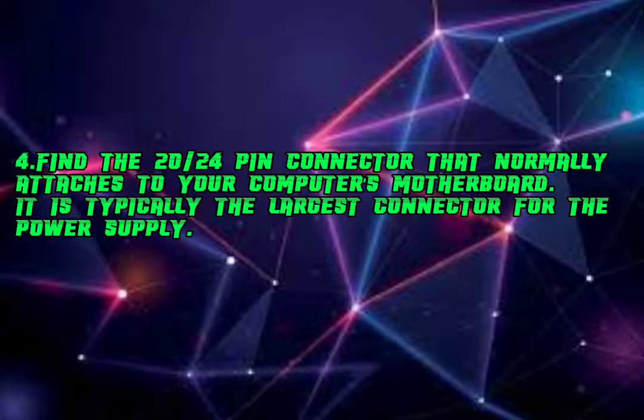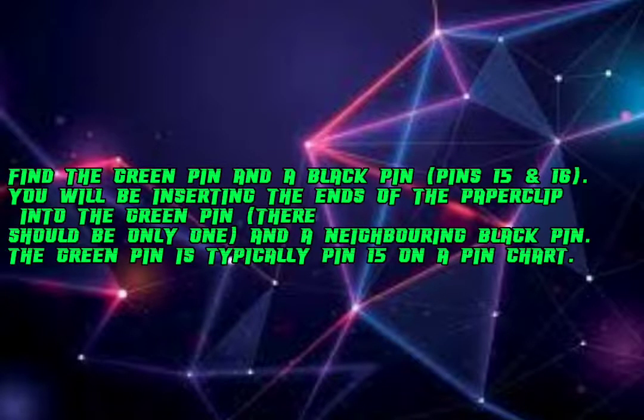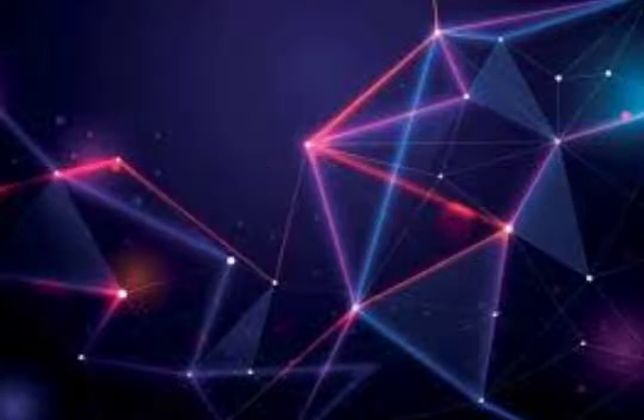4. Find the 24 pin connector that normally attaches to your computer's motherboard. It is typically the largest connector for the power supply. Find the green pin and a black pin, pins 15 and 16. You will be inserting the ends of the paperclip into the green pin. There should be only one, and a neighboring black pin. The green pin is typically pin 15 on a pin chart.